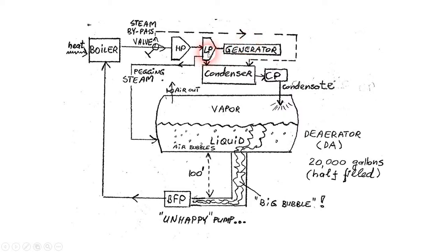After the steam went through the turbines, it condenses in a condenser. Condensate pumps dump it back to the deaerator. And then at the deaerator, the fluid stays in saturation, but when there is an upset, when the generator doesn't have load on it, then steam gets bypassed across into a condenser, and it gets interrupted, pegging steam not to go anymore to the deaerator.